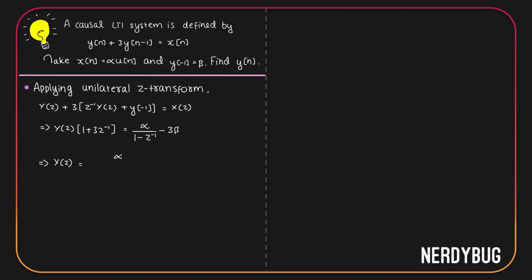Then we get alpha divided by 1 plus 3z inverse multiplied by 1 minus z inverse minus 3 beta divided by 1 plus 3z inverse. This is the Z transform of the output of the LTI system given in the question.